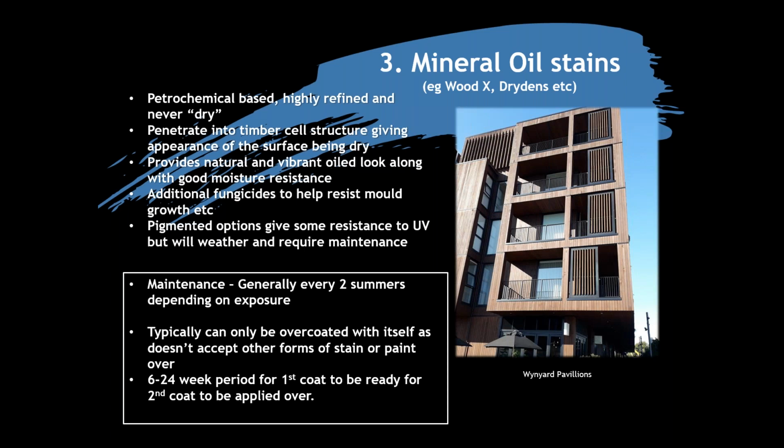And the key to them is that while they might be touch dry on the surface, they actually never dry. So underneath the surface, they're penetrated well into the timber structure. They're sitting there, they're not dry. They provide a magnificent, vibrant oiled look, and they give fantastic moisture resistance, good fungicides, and in the pigmented options, they provide some resistance to UV as well. But as with all stains, they require regular maintenance. It's generally every 2 summers. So